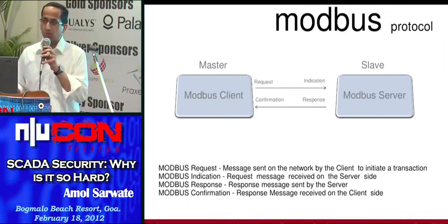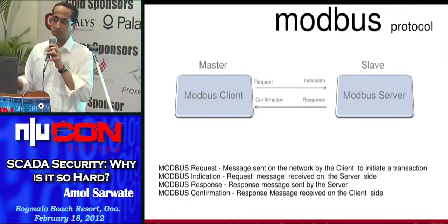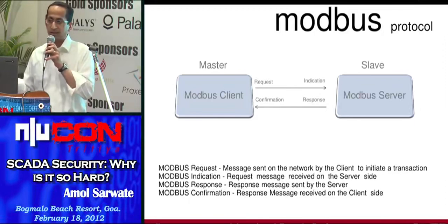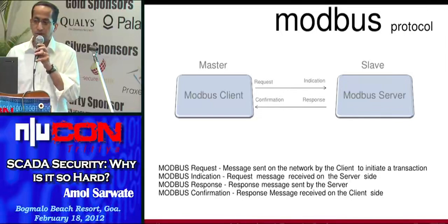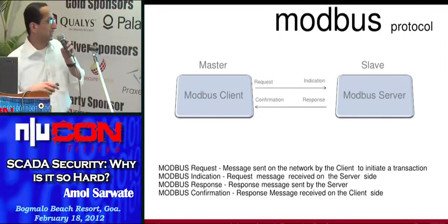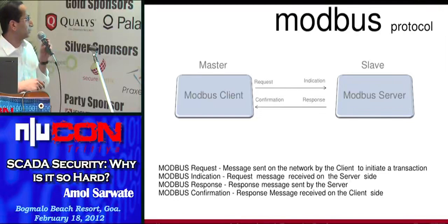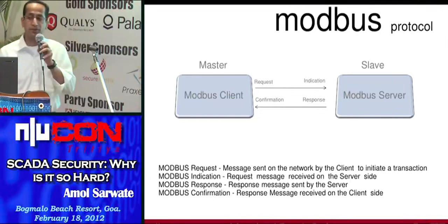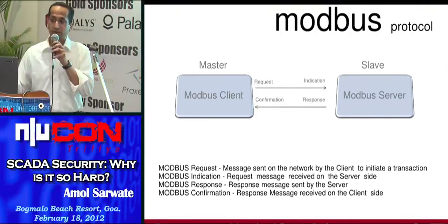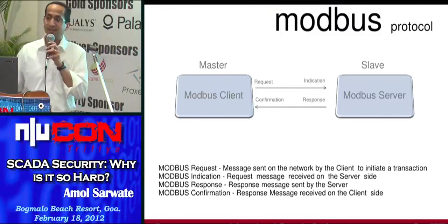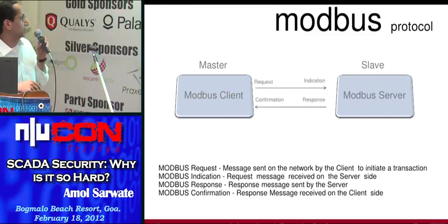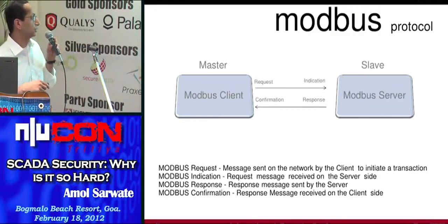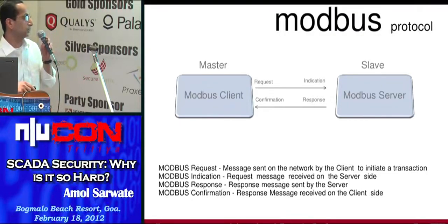If you know any simple protocol, Telnet, FTP, SMB, any simple client-server protocol, you can easily master Modbus. It has almost the same thing. There is a Modbus client. The only difference between a Modbus client-server communication and, for example, a Telnet or FTP client-server communication is that in Modbus, the client is called the master, while the Modbus server is the slave device.